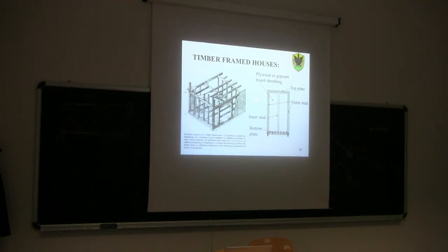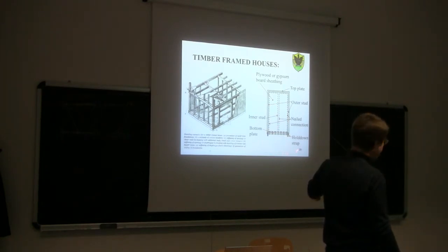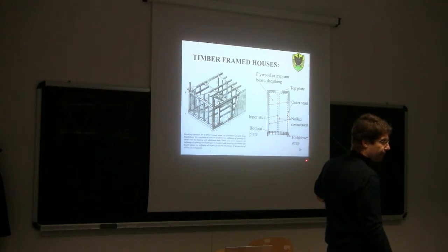And then, of course, this wall, that now is statically determined, has to be connected to the floor underneath or to the wall underneath, or if you are on the foundation, directly to the foundation. This connection to the foundation is achieved using some bolts along this horizontal member and using some hold down straps. So some pieces of steel, like plates of steel, that connect the outer studs directly to the foundation. Okay?